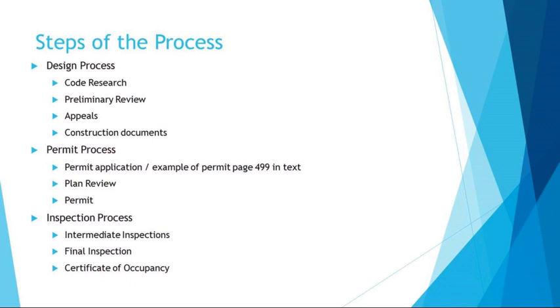An example might be if I'm renovating an existing college facility, I want to concentrate on the code requirements for business occupancies. Yes, it is a business occupancy. But if the project includes renovation of the cafeteria, the requirements are for assembly, and they may have to be reviewed as well. There may be a couple of occupancies within one project. A majority of the research should be done in the programming stage of the design process, at the same time the client and building information is being collected.